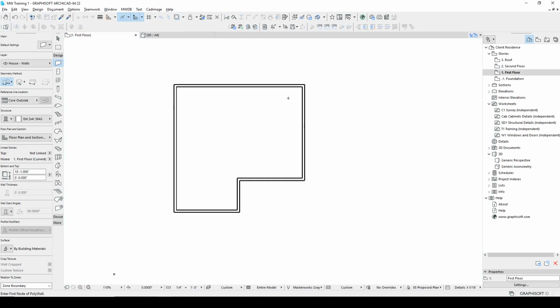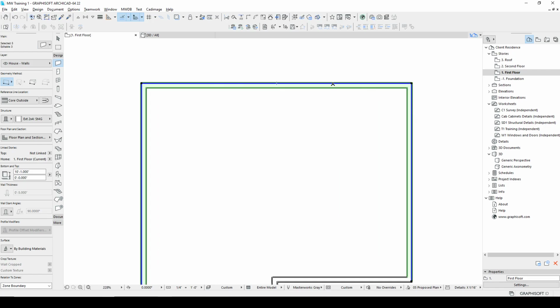So now, just exactly like you were adjusting the lines, if I select chain lines, I get some pet palette choices here. I can curve this. I can add a node. I want to add a node here, maybe at 4 feet. And then I'm able to pick this and extend this out 2 feet.